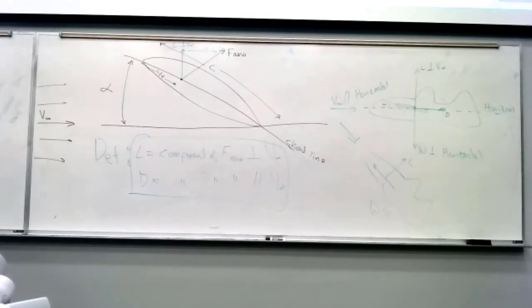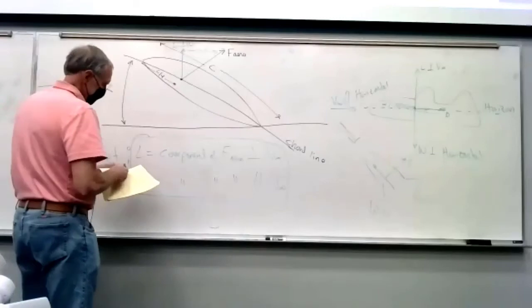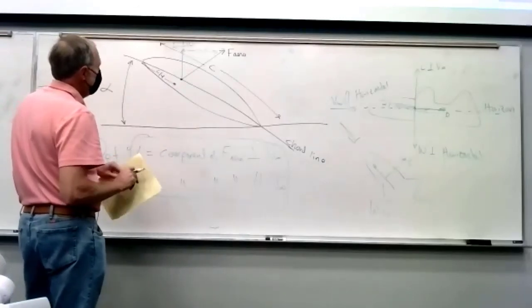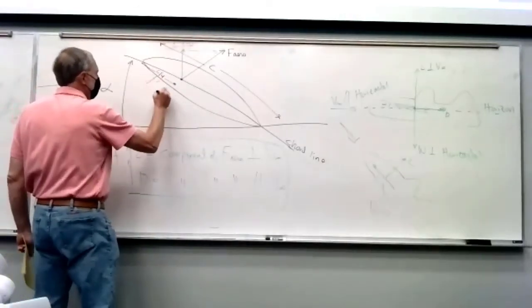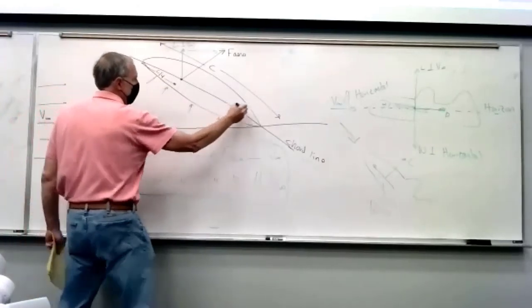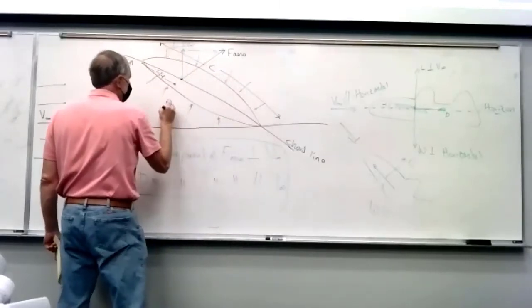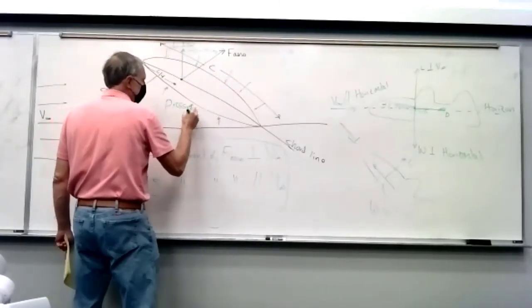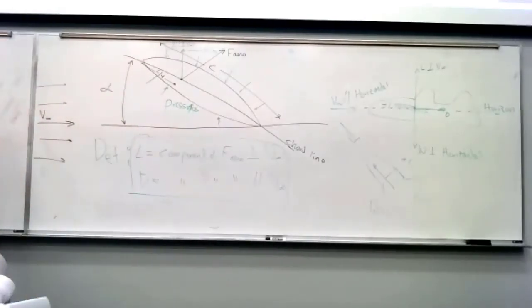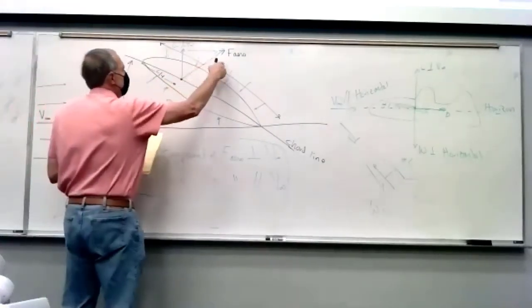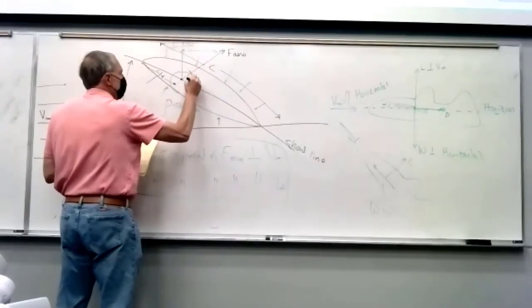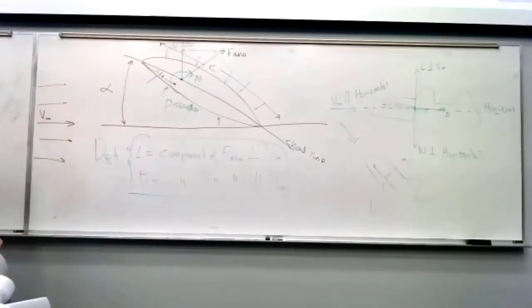All right, the other thing that we need to talk about is that because the lift and the drag and the aerodynamic force are caused by pressure forces all over the upper and lower surfaces, these are all pressures. In statics, you guys studied distributed loads, right? That's what this is. You have a distributed load all around the upper and lower surface. And so in addition to a net force, you can get a moment from the pure. You either get a field couple or you get a distributed load.